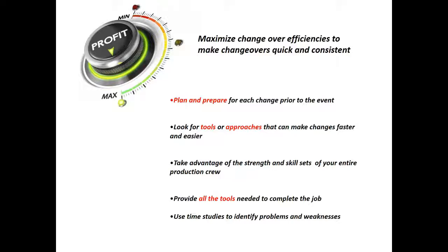Situations arise where tools are being searched for, tools that you need are not there, so other methods must be used that take more time. You want to eliminate any time from your setup that you don't need. And another important thing is to use time studies in regards to your setups to identify problems and weaknesses. Quite often, the time study will give you tools that you can use to improve your setup time and reduce your downtime.